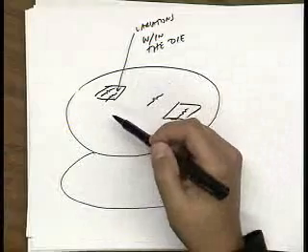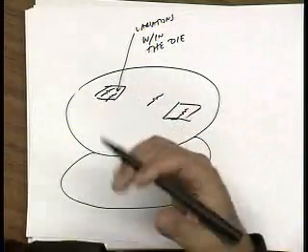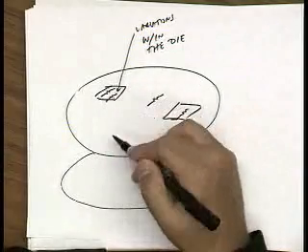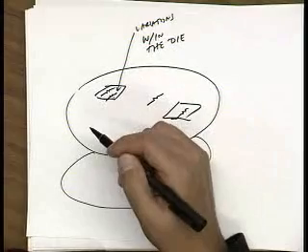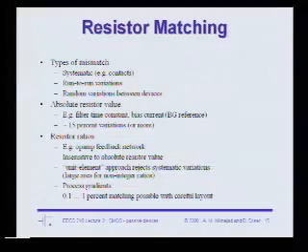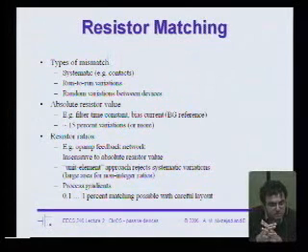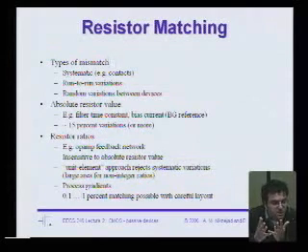So that's really a big reason for using resistor ratios, because now we don't depend on absolute values of resistances, but they're ratios. And ratios should track very well. Okay? So let's switch back here. So that's why we're going to use feedback networks, right? Feedback networks naturally give us transfer functions which are inverse of our feedback factor, which is some kind of function of ratios of resistors.